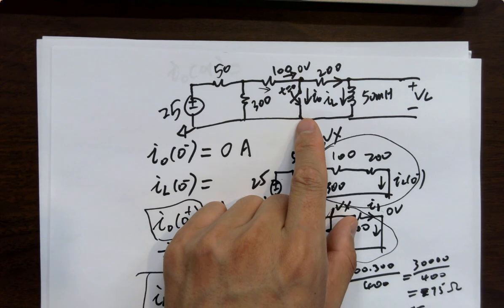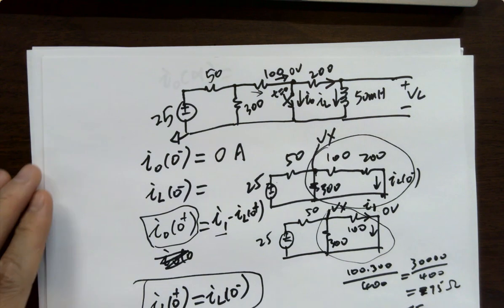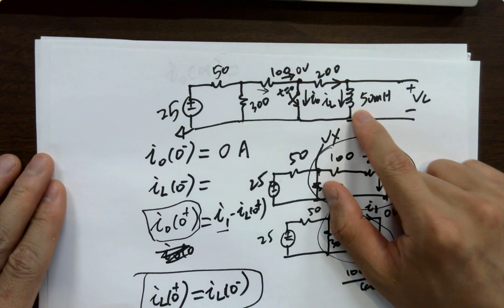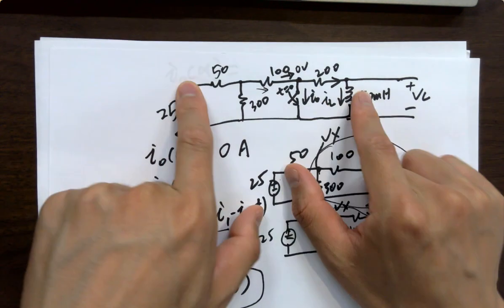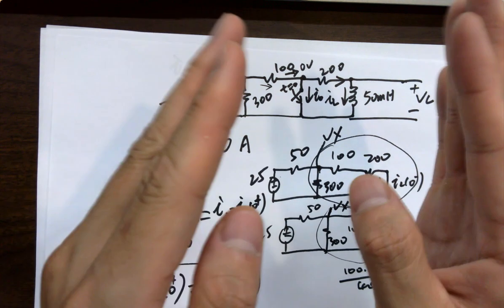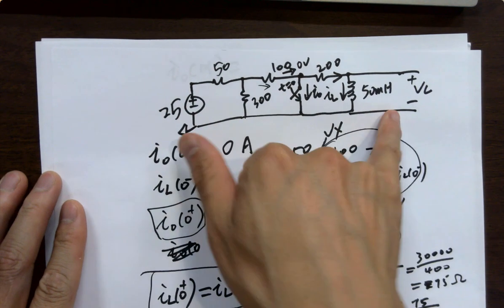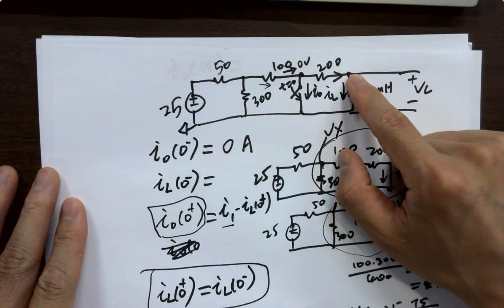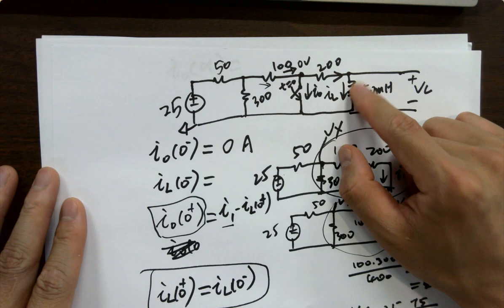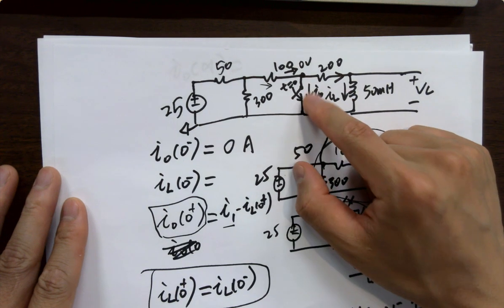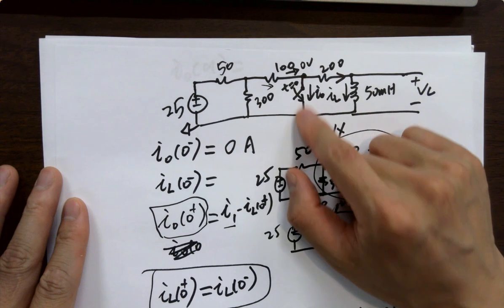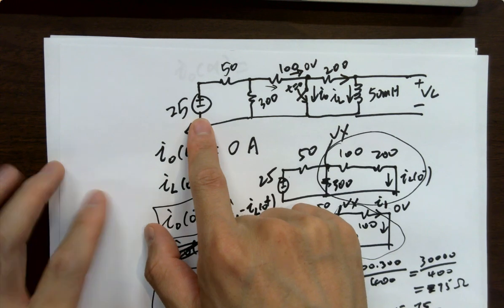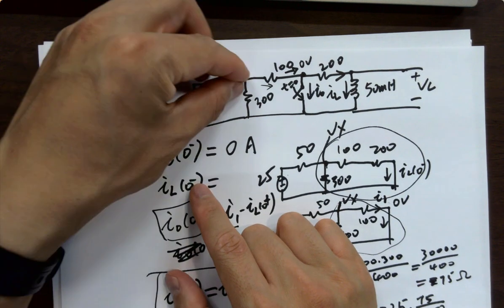So what's the equivalent circuit for that case? You close it, right? And this one discharges, this one is affecting whatever. I don't care about the details for now. Eventually it becomes a state where nothing is going to change anymore: DC circuits. So this becomes what? A wire, okay? What is this though? A switch. It's also a wire. So what's happening? Do I have a source here? No source, right? Do I have a source here? Yes. So it's going to pump current in here and split.